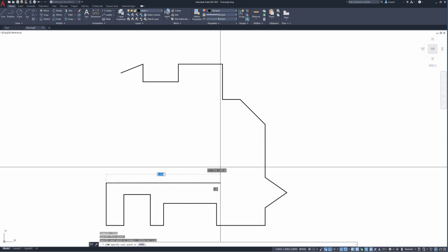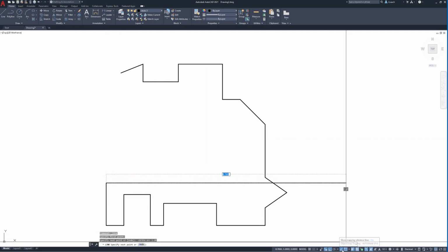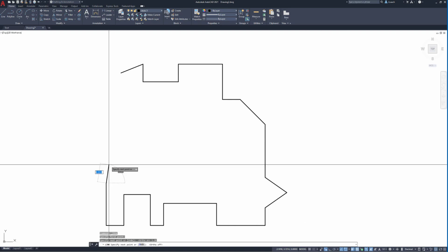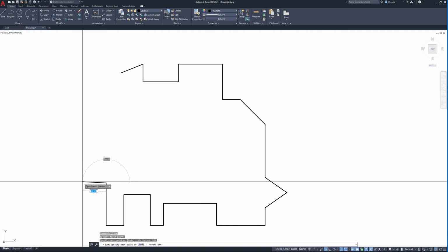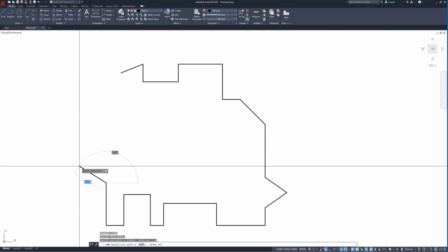And then I'm going to turn ortho mode off, which is where am I? Here, this one. Then we're going to come over a little bit to the left and up. So this is going to be a length of 1.50. Press the tab key. And then I need to figure out that angle. So that's going to be 180 minus 38. I can't do math in my head. I need a calculator. It is what it is. 142. So that's going to be 142.